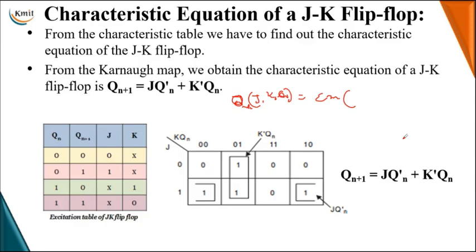So now that 1, 4, 5, 6 I am going to take here as minterms, and upon mapping your function, we obtain this using the K-map method.